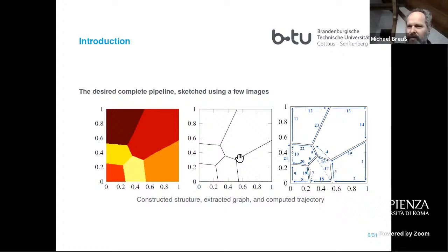what you can do, of course, is print double ways. Yes, sure, this can also be incorporated in a mathematical model. But basically, then you have to jump. And this is also not good in many manufacturing processes, if you cannot go along a continuous line. So you want to minimize these jumps as much as possible. And it is also, of course, a matter of printing time. And so the question is how to build these optimal paths,